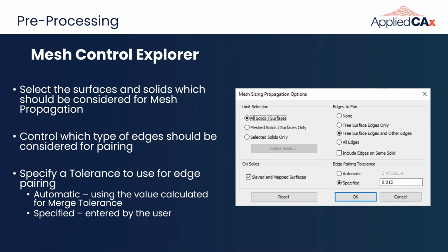Previously, for surface modeling, we would be creating a bunch of mid-surfaces and then using non-manifold add to join them all together into one continuous sheet solid. That's no longer necessary. I'll be honest, I'm still getting used to this technique, so I'm not 100% converted to the new technique here, but it is really nice, and I've surprised myself at certain times working through a simple model and realizing, oh, all my elements are lined up. I can skip some steps here.